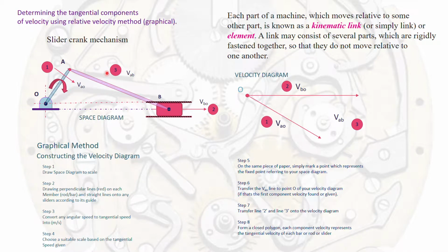Then the next one is your third, that means the member or the link AB. So you draw this line perpendicularly to the line that joins A and B. The arrow you don't put first, you don't know which direction yet, so you just refer to the line only. From either end, if this is your horizontal line and you were to draw this line over here, it will not meet, and then it becomes infinity. It will never join.